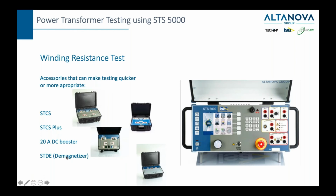One thing to mention, winding resistance test is often the last test you do. It is the last test you do because you magnetize the core, and after that, you need to demagnetize that core. Otherwise, you might have issues. But let's go back to the winding resistance test.